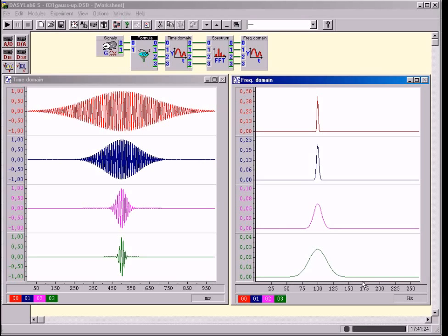Theoretically, every Gaussian pulse lasts infinitely long because the Gauss function reaches the limit value 0 at infinity. In spite of that, the Gaussian pulses have in each case a different time duration delta t, as well as a different bandwidth delta f. Therefore, the time duration delta t and the bandwidth delta f of a Gauss pulse must now be defined in a practical sense.